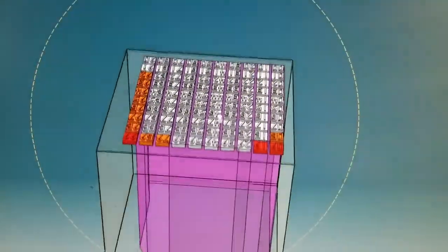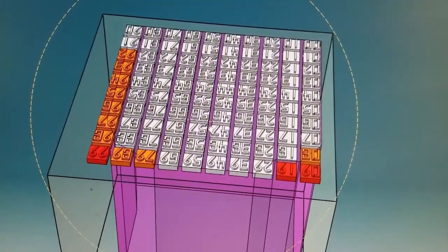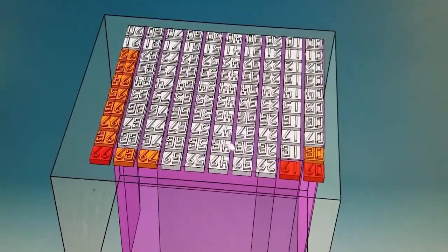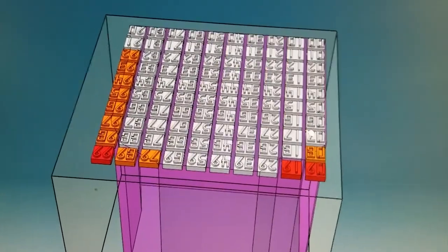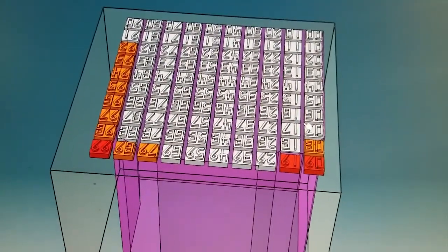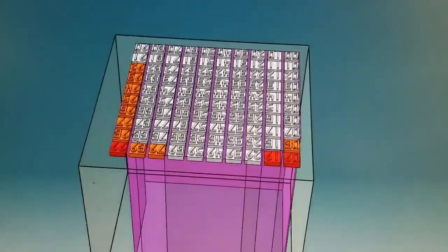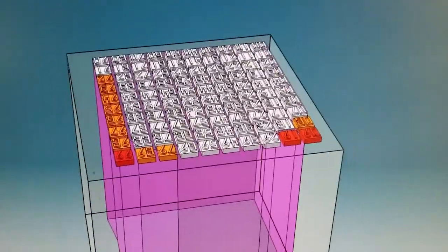But when it goes into Sintratec, this is the orientation that these come into. I export these STLs, which go into Maya, and then I use my exporter script to make sure they're oriented correctly into Sintratec Central, and then I reset all the XY coordinates and save it as an STEC. So I'll post the STEC file that I made of this here.